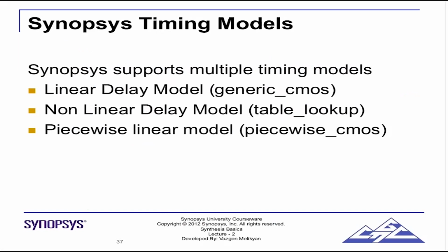Now, before looking at the timing section, let's talk about the Synopsys timing model. Representing the pins, telling the tool, writing the pin direction, calculating the output cap, input cap, telling the function, they are all simple jobs. Why? Because there's only one single value to be compared. The input cap will be a single value, the output cap will be a single value. But what about timing? Timing is not a single value. Timing depends on how much load you are driving, how much transition you are getting at the input, and some other parameters.